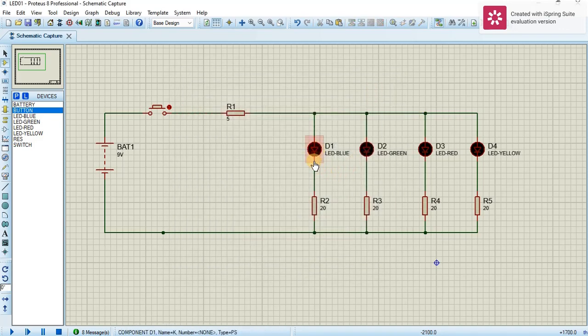So whatever we are having must be less than 10 milliamps in that branch. So we are going to use a multimeter, an ammeter and voltmeters to measure the current, and then we try to adjust the resistance and see if there's any change in the glow.